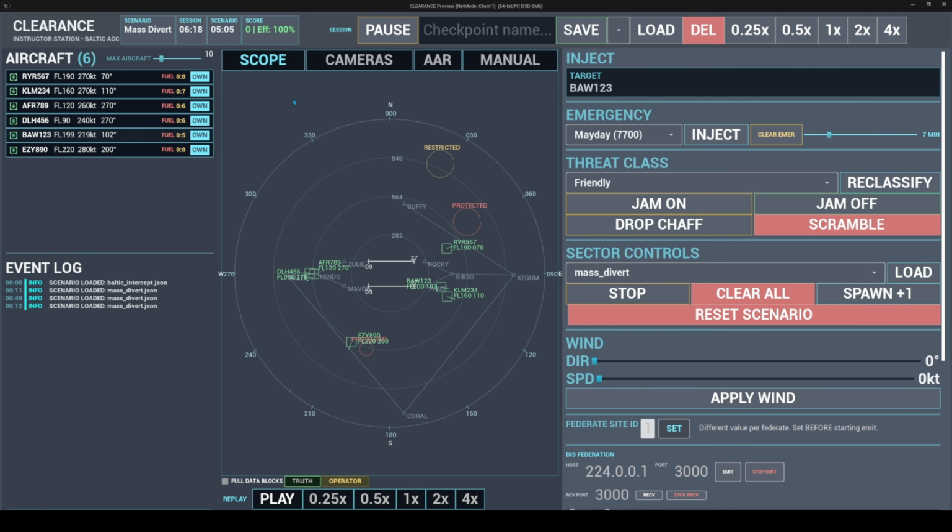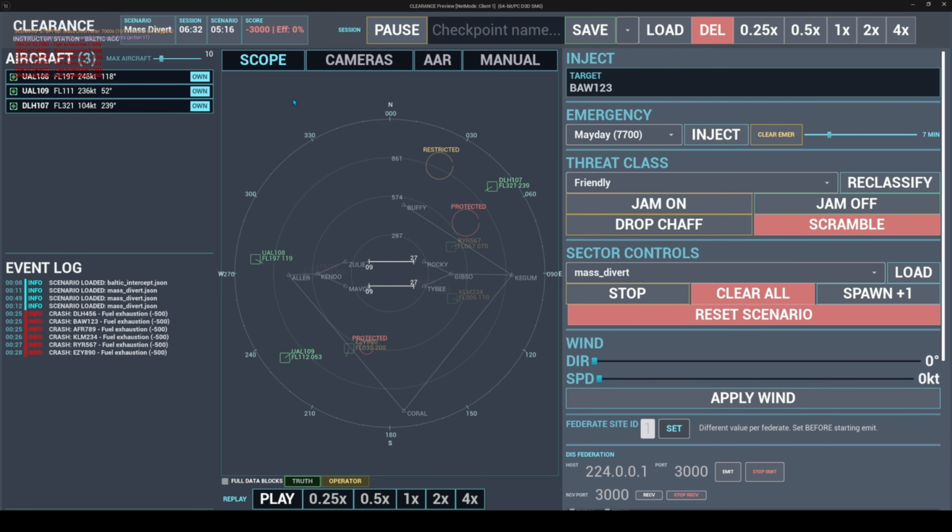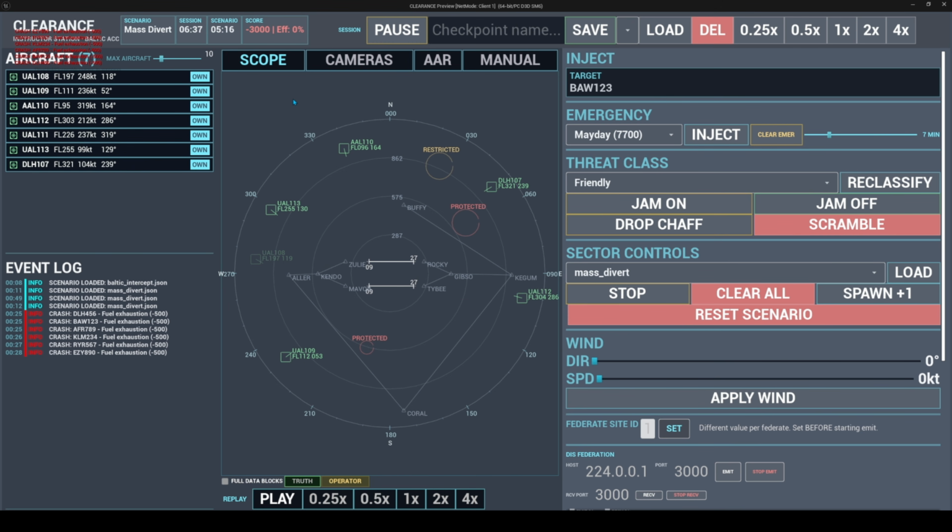And back to the radar side of things. These blips are refreshing twice a second. Each refresh is one full CPI through the Simulink chain, beamform, Range-Doppler, CFAR, across every aircraft in the sector. The DSP produces range and Doppler for every detection. My matching layer unaliases range and maps each detection back to its source aircraft.